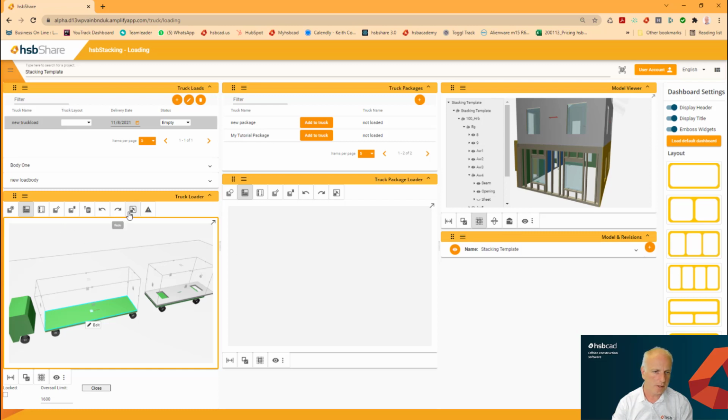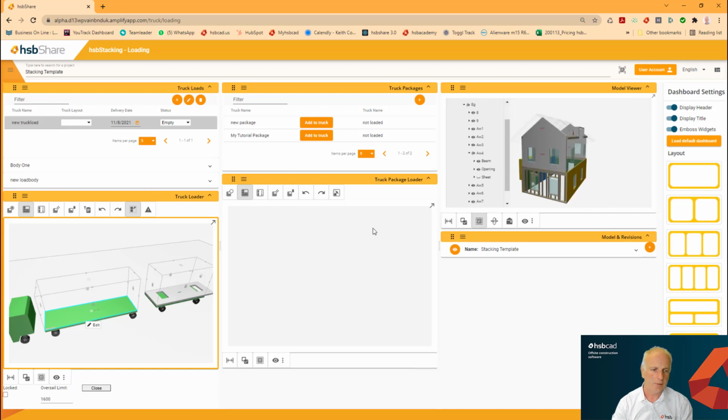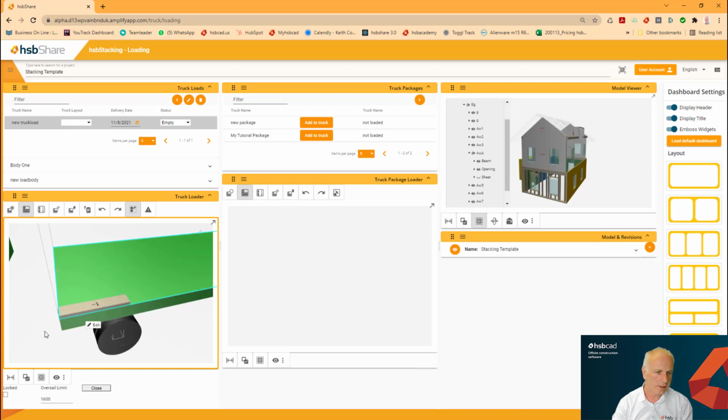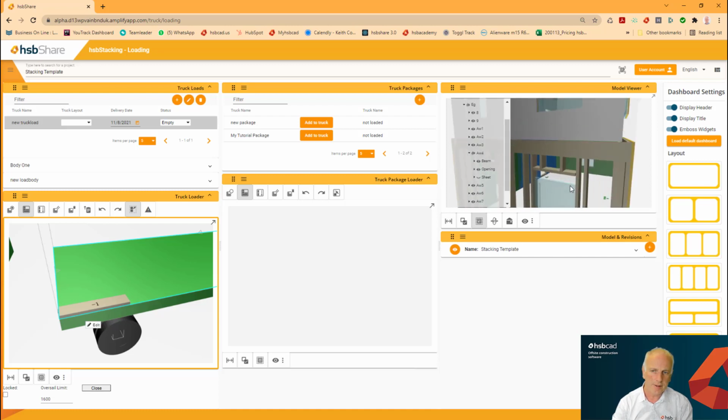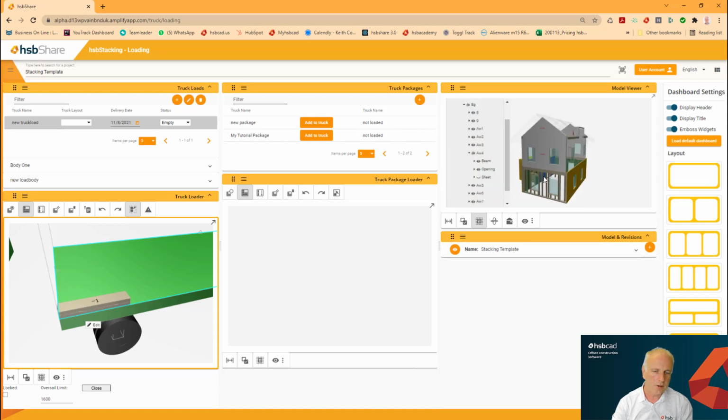Furthermore, what I'm going to do up here is also turn on the snap on entity. So I want to be able to snap to a point in this case. So back up here, I'm going to pick this particular beam on top of the opening. I'm going to zoom in here, and you can now see it snaps the entity here onto this. So this is an individual beam which is taken from this particular element here. Let's pick the next one, and you can now see it is allowing me to stack those elements.